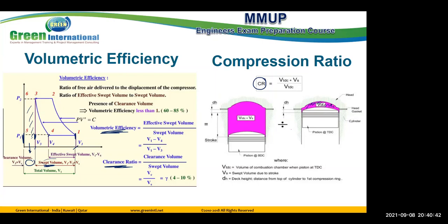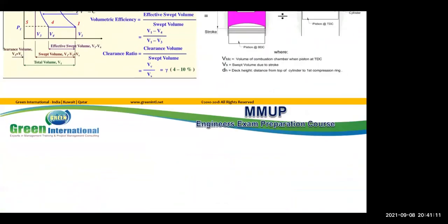We tend to reach the maximum, which means 0. If you add the swept volume, this is almost the total volume. So if you divide the total, which is swept plus clearance volume, by the volume at top dead center, this is the compression ratio.